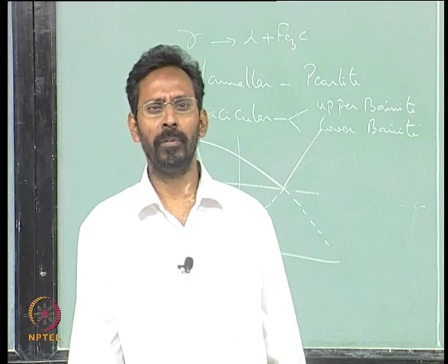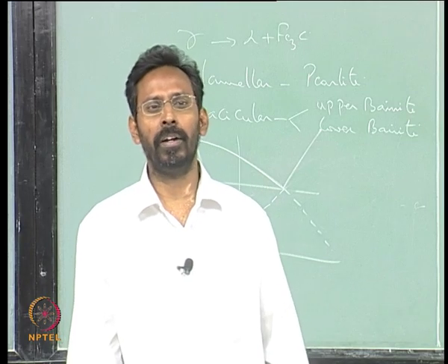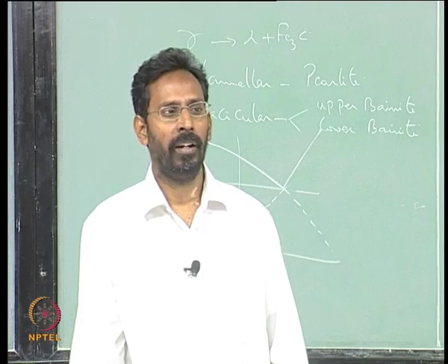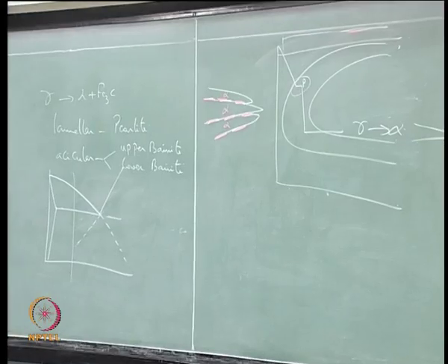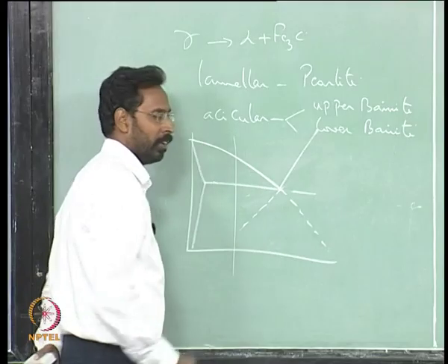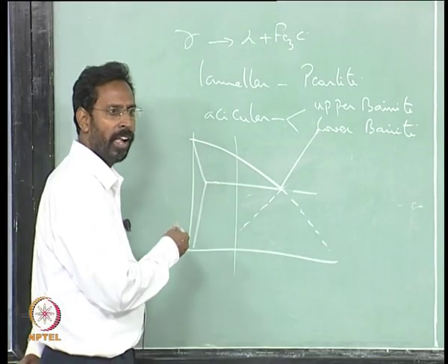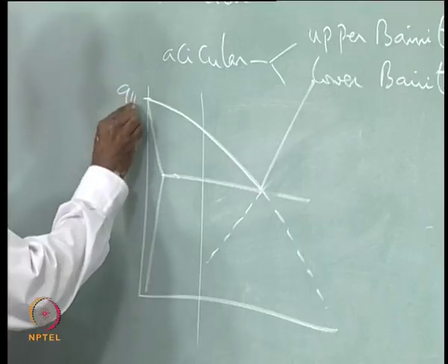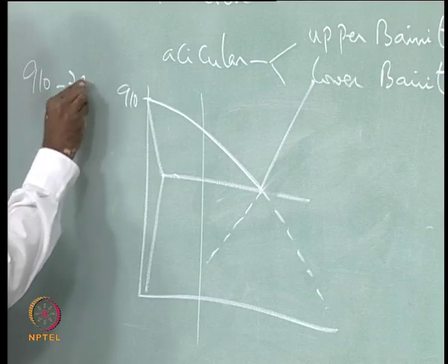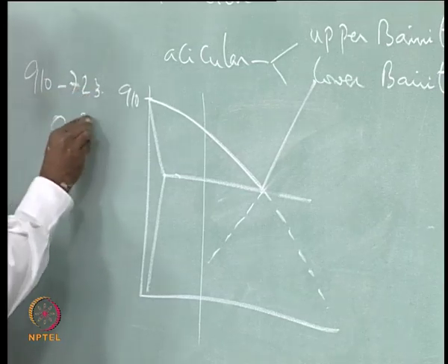That is also a phase transformation. Gamma is giving you a cementite, there is a phase transformation. Simple geometry, that is it. You should know that here. A3, what is this temperature? 910 let us say. So from 910 it is coming to 723 in 0.8%,